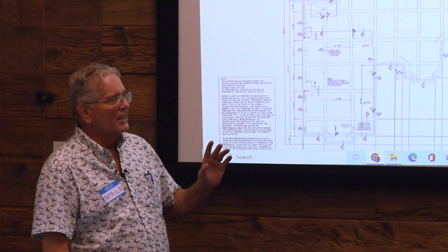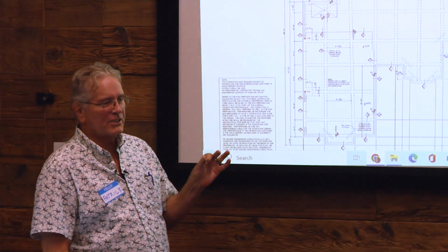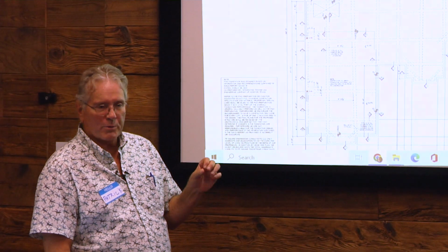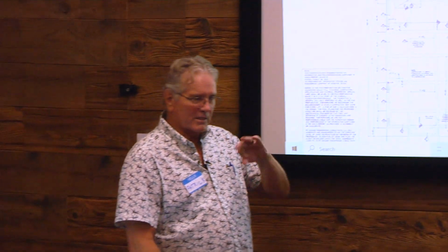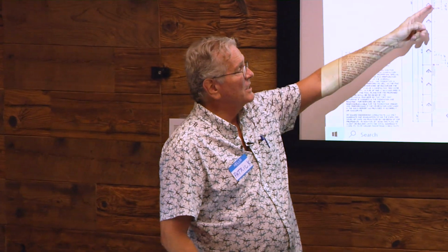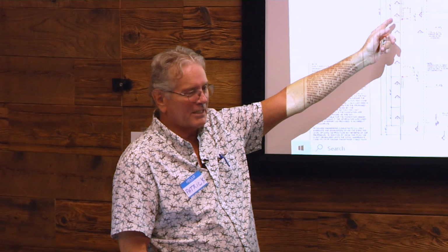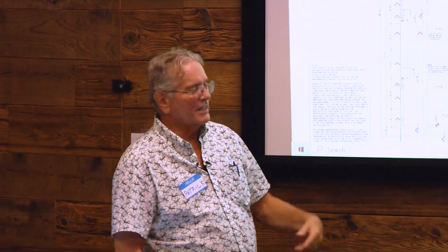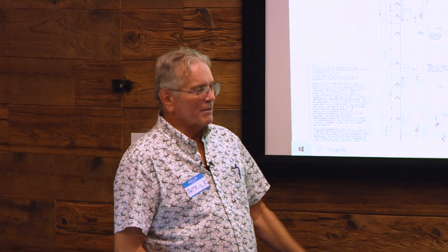We got it done. The key is have the engineer do a pre-pour inspection and sign off on your foundation. He didn't sign off on it. He said this needed to be corrected. At 4 o'clock the morning of the pour, they were correcting this because they didn't show up the day before. We had all these flashlights on it and me standing there taking pictures.